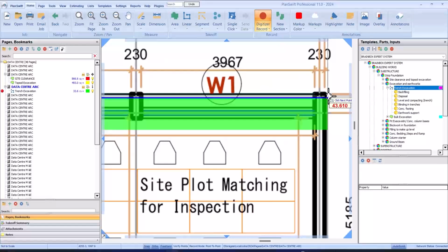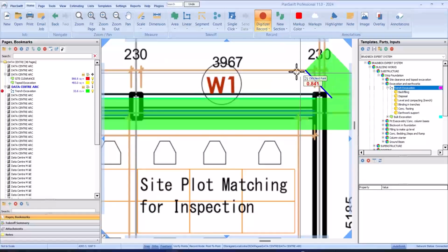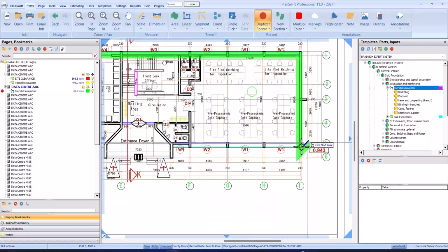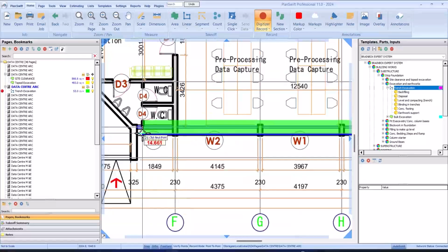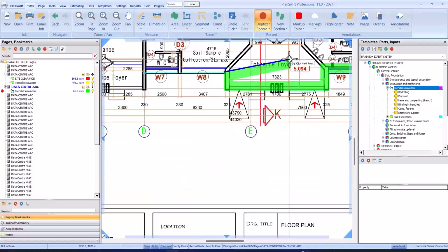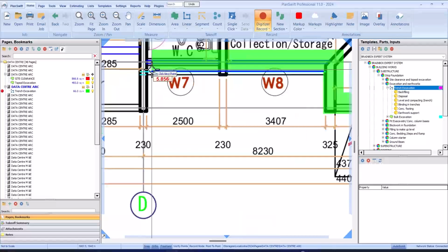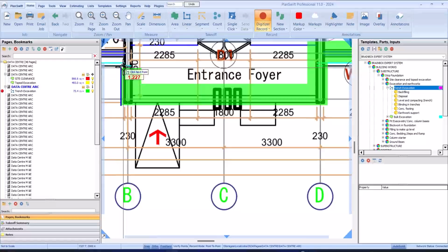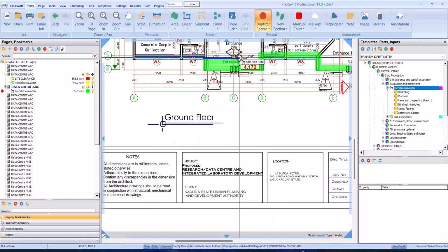But in this case, whereby you don't have structural drawing, you are going to take it completely. So when you take off for your pit excavation, then you deduct your pit excavation from the trench excavation, because you don't have any areas whereby you can identify where your columns are and where there's no column.